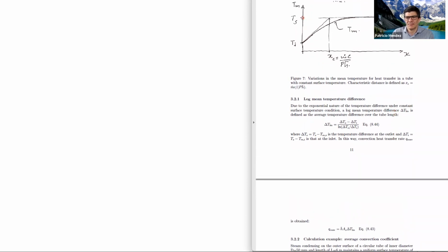You see that the surface temperature, the pipe temperature, right, is the hot surface, and the fluid have a difference. And here we have high heat transfer. And as the fluid progresses, the temperature difference is changing. So how do we assign an amount of heat transfer by convection when the temperature is changing? That's not trivial. We want to say H delta T, but delta T is changing.